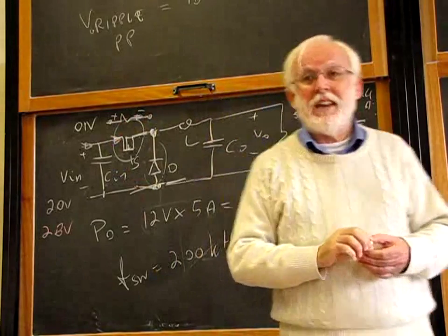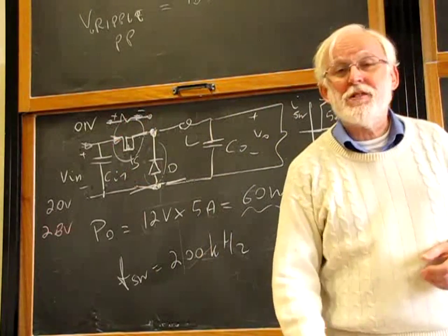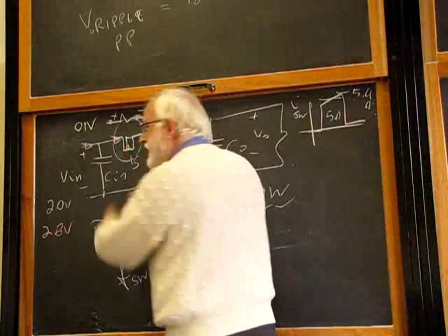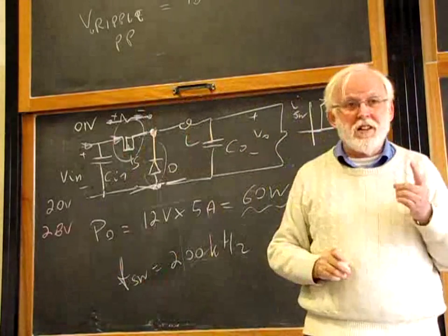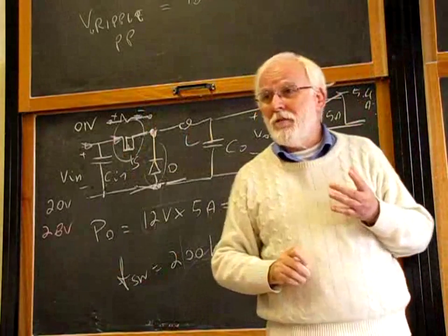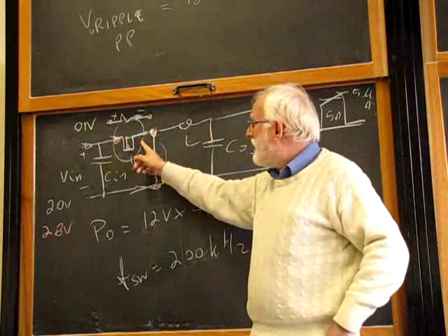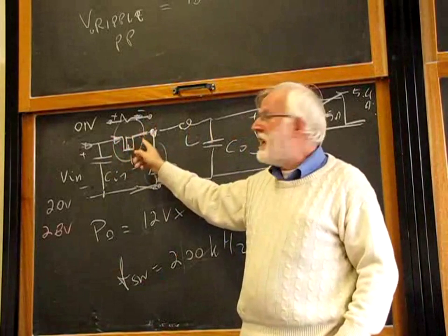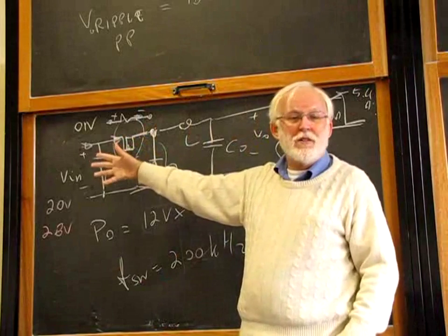You could say, okay, I can pick a very good MOS transistor, a MOS transistor that gives me a voltage drop over here that is only 1 millivolt. Is it good? 1 millivolt of voltage drop means that your efficiency loss is negligible. 1 millivolt out of 20 volts, you don't see it, you can't even measure it.